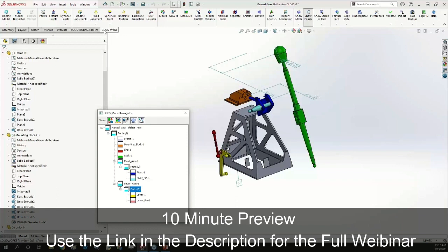And inside of that 3DCS MVM tab, we actually have, I believe, close to, not all, but close to all of the buttons that you'd have in the normal 3DCS tab, in addition to these additional buttons that would normally be a part of the 3DCS Mechanical Modeler add-on toolbar. So we're picking and choosing some stuff from Variation Analyst, some stuff from Mechanical Modeler, and we're combining them together to put together this nice MVM package for you.